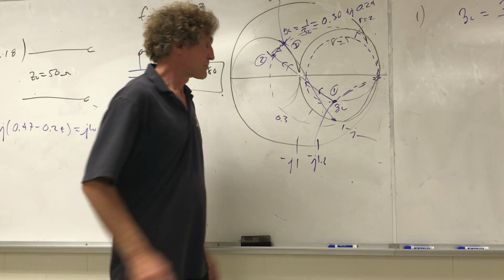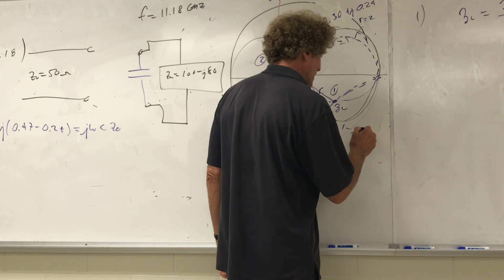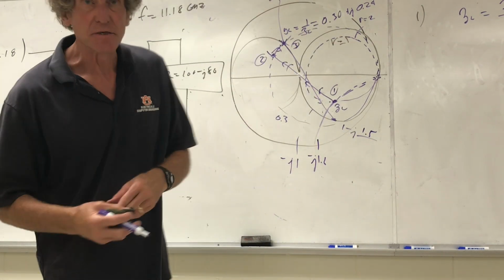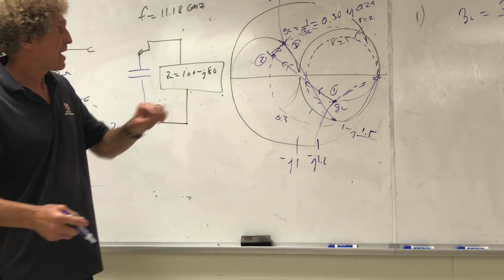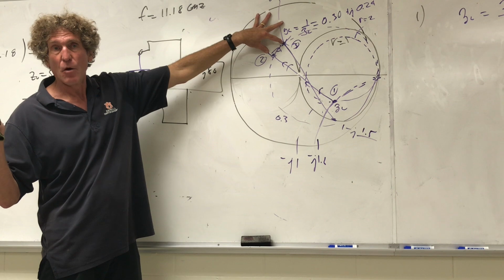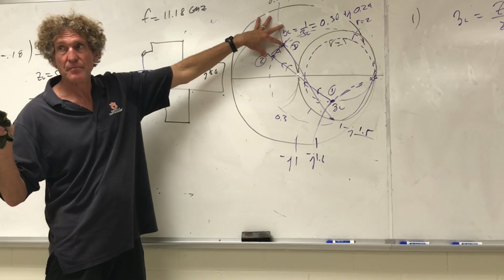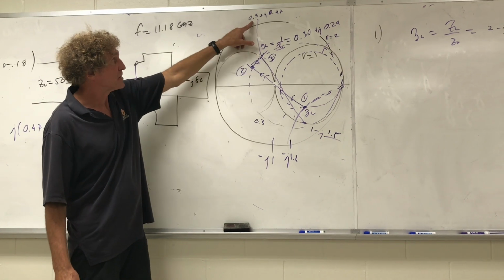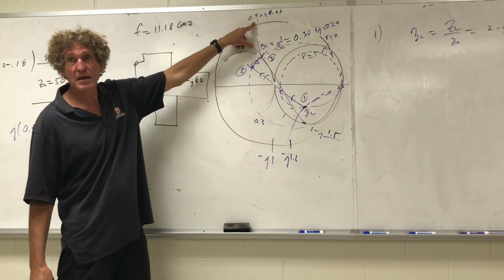Wait, so you take 1 over, say it, who's that? What'd you take to get back? All right, listen, everybody. I'm here, right? Now remember, that's the y domain, that's admittance. 1 over admittance is impedance. Just take that value, which is going to be 0.3 plus j 0.47.